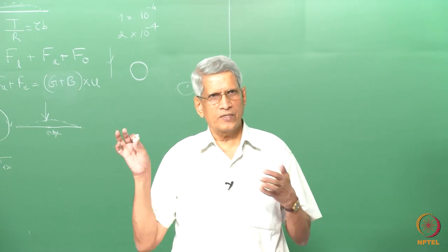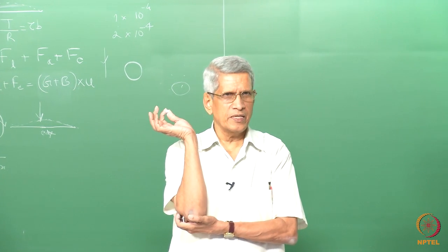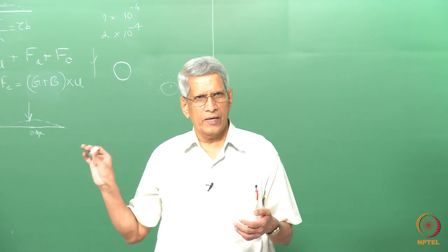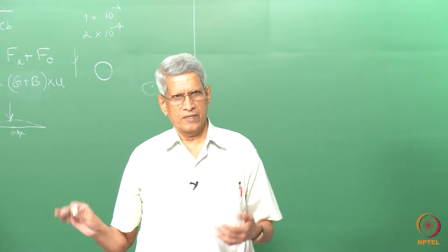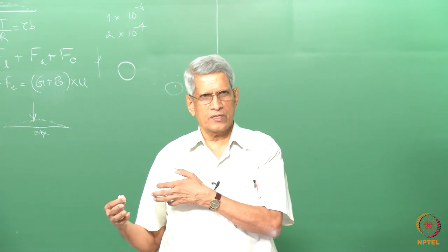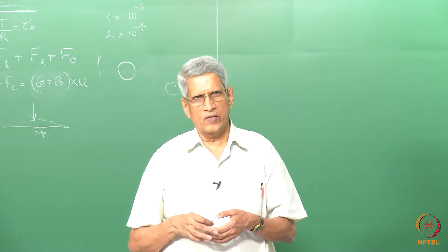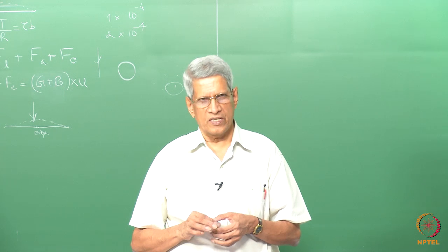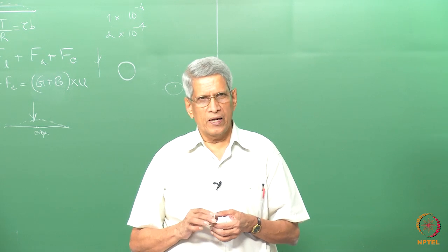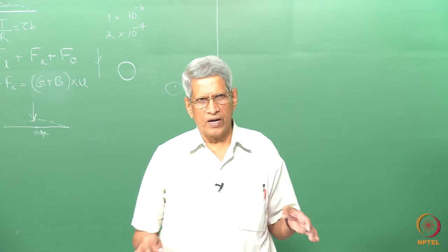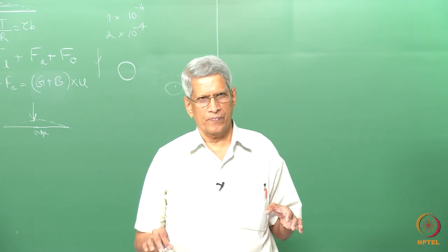Then, when excess vacancies are generated in the material, what will be the effect on generating stresses? As we discussed just now, even a small increase in vacancy concentration is going to generate very high stresses. And what are the implications of these stresses? This is what we have considered in this lecture.